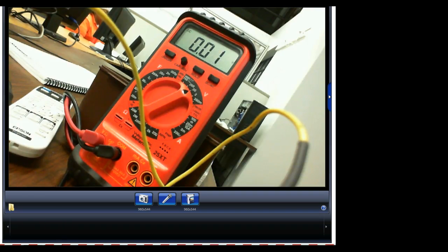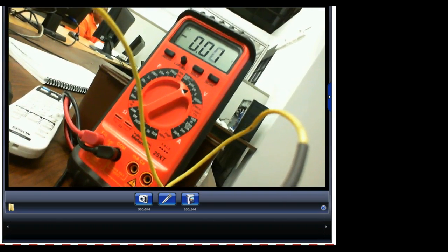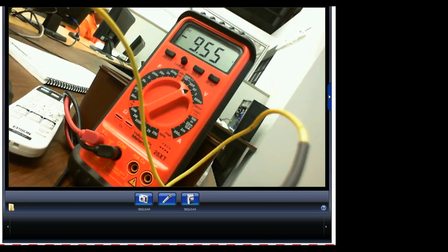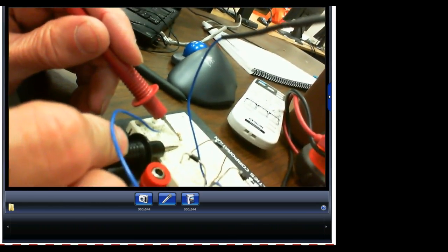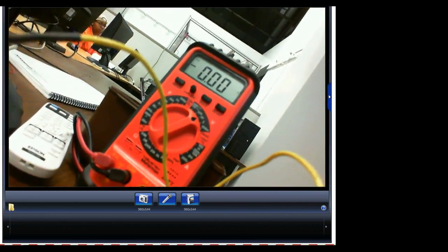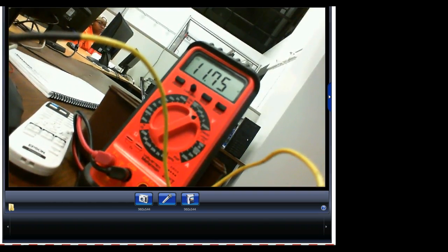And we should expect around 11 volts. Did y'all use the whole calculated value, or did y'all use the 0.9? You did all of it? So here's what we're measuring. I got my meter. By the way, on a bridge, it makes no difference. It depends on what you consider to be common. If I consider this to be the common, then it measures a minus voltage. If I consider this to be the common, it measures a positive. So 11.75 volts. Not too shabby. It's not too bad.